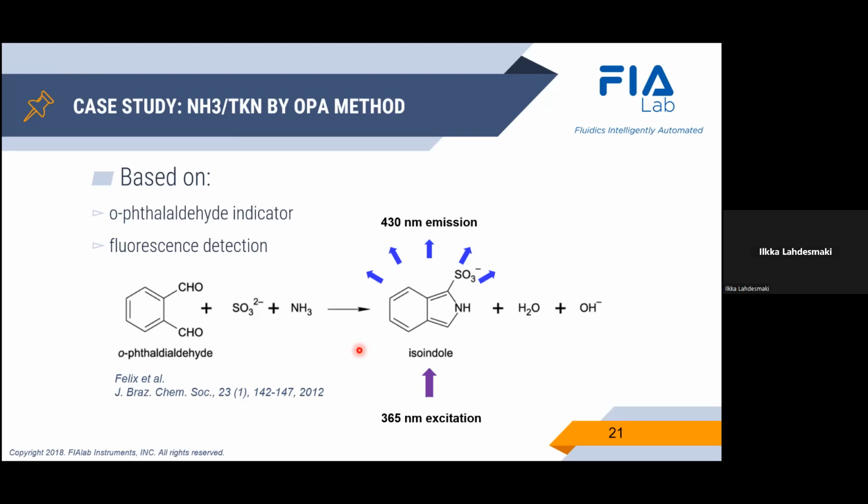The advantage of fluorescence being that since our illumination light in the UV is in a different spectral region than the emission light that we're collecting, we're able to optically isolate these two light ranges, and that way make our measurements against a dark background, giving us tremendously more sensitive measurement conditions compared to absorbance.